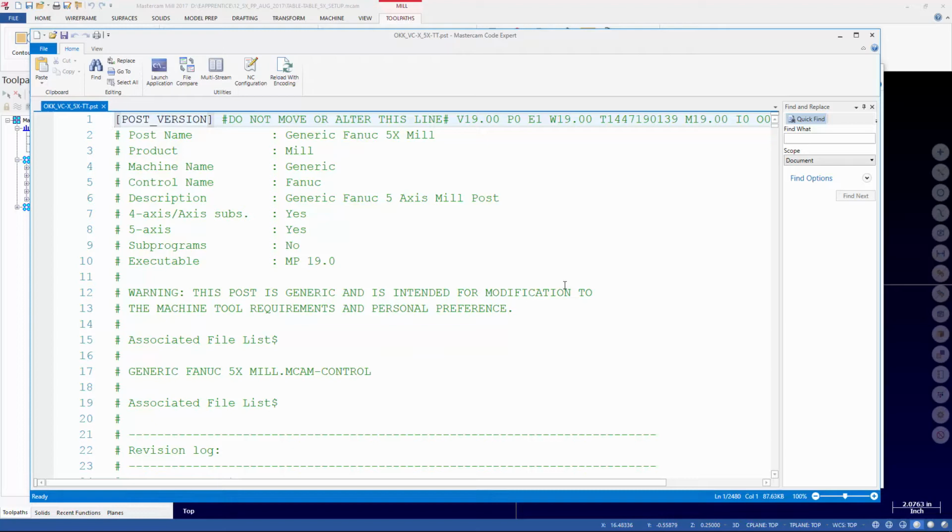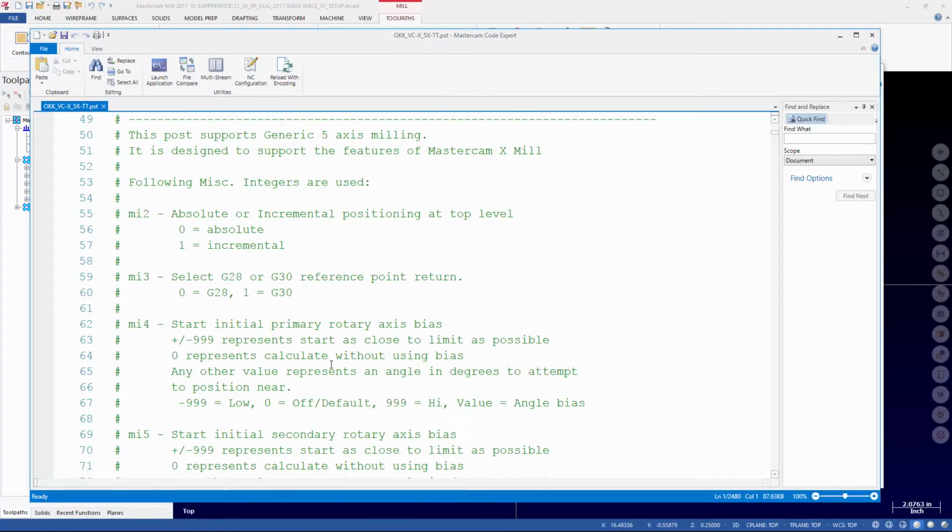But yeah, I think personally it is best practice to set them all to match. That means if you get a new copy of Mastercam and there's this new generic post and you want to use it, well, now your machine definition file already works. So you can just plug in the new post. It's going to read your settings from the MD. Boom, you're off to the races. But we've got to focus here on configuring this post.